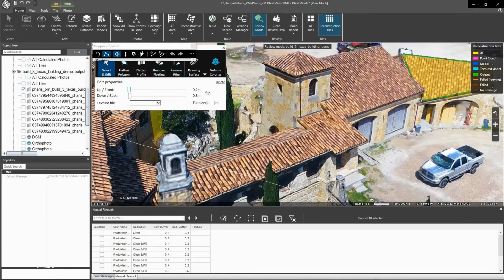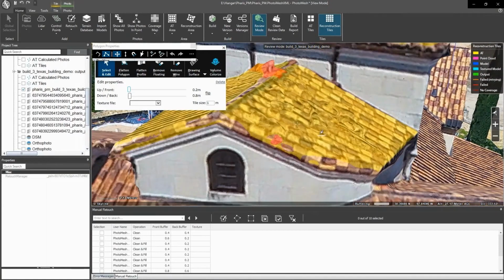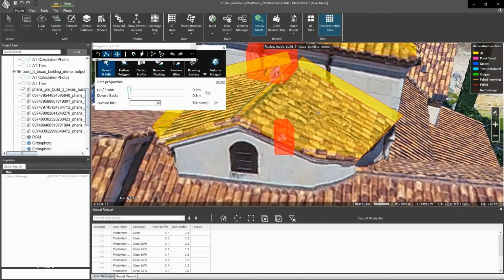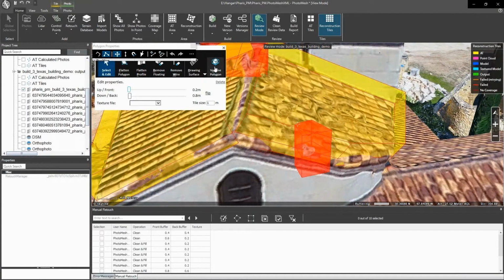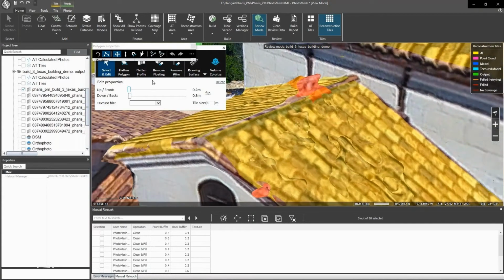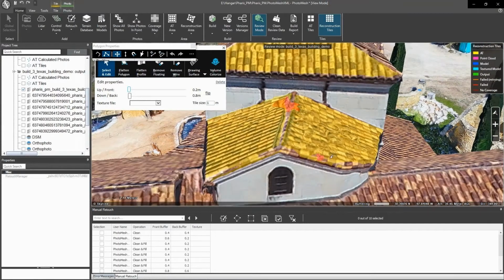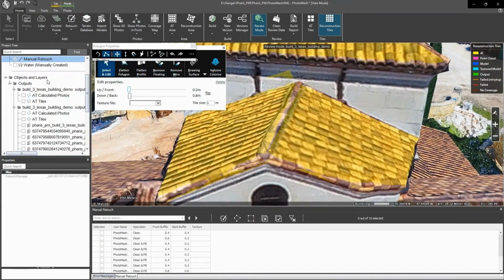So to give you an example, say over here on the roof line, there was a little bit of noise. So we can see I drew a flattened polygon on these two sides of the roof, and these are the areas that are being affected. And here I just put a small remove floating component to clean up this little patch. And we can look at the result and how it cleaned up the roof.